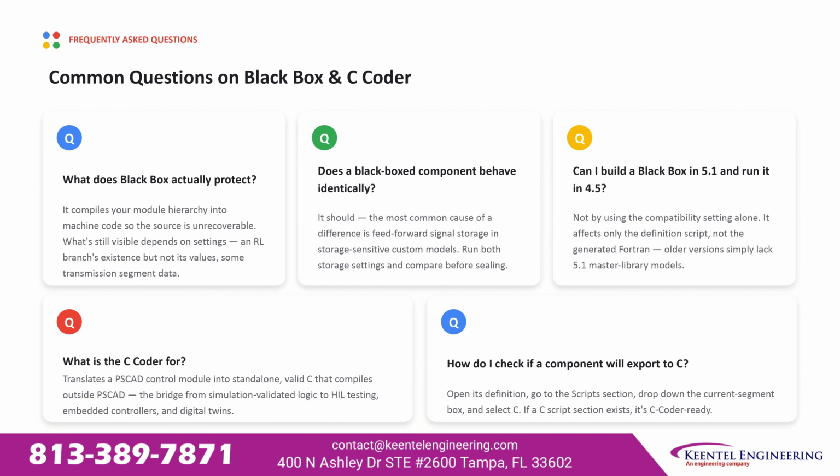What is the C coder for? It translates a PSCAD control module into standalone valid C that compiles outside PSCAD, the bridge from simulation-validated logic to hardware-in-the-loop testing, embedded controllers, and digital twins.